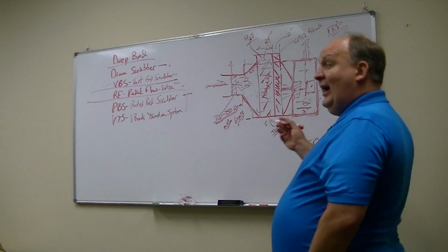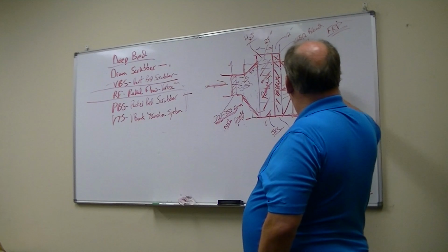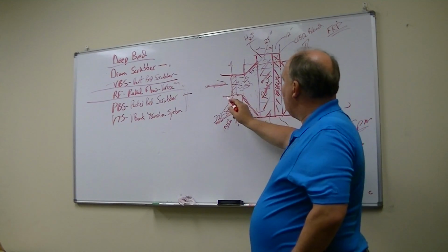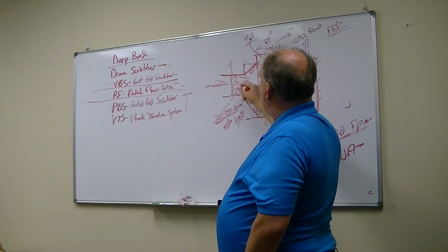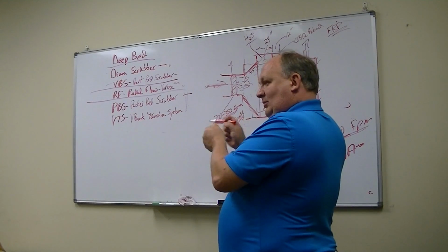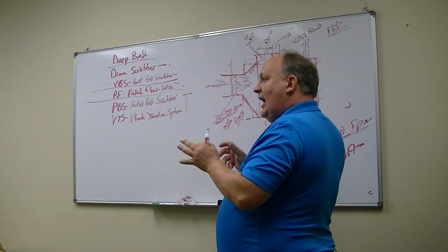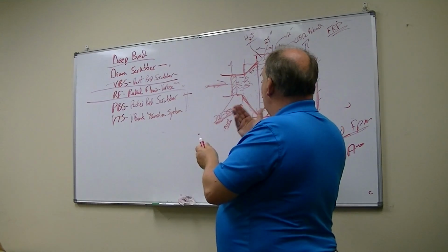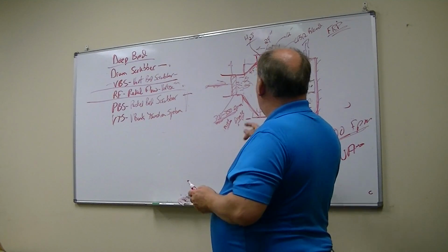Keep in mind when you're designing the system, this door here is going to be under pressure. The entire system is under vacuum because you're pulling the air through. So the door for the mist and grease filter will keep itself shut because it's under vacuum. You don't have to worry so much about making it super airtight. It's going to keep itself pulled shut. We should still make sure we make it nice and tight.